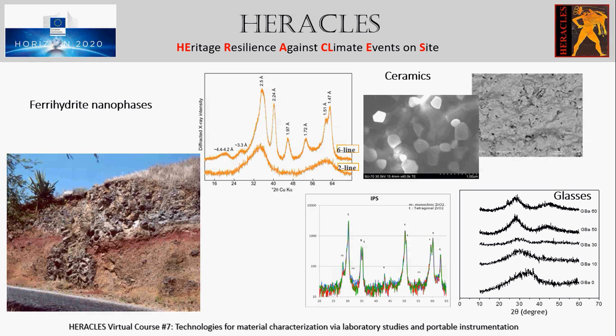As can be seen here, for instance, in the case of ceramics, where there is a precipitation of crystalline structures inside an amorphous glass. Even when we are studying amorphous structures, some information can be gathered, as it happens here, where we mix different compositions of glasses and where we can see two amorphous bands forming, indicating the formation of two different glasses in the mixture.